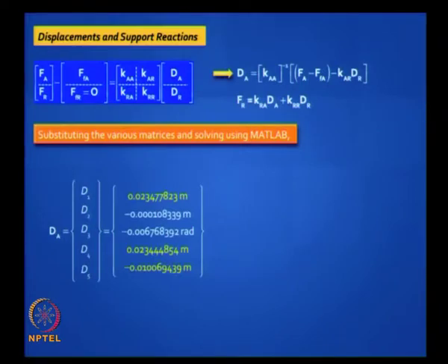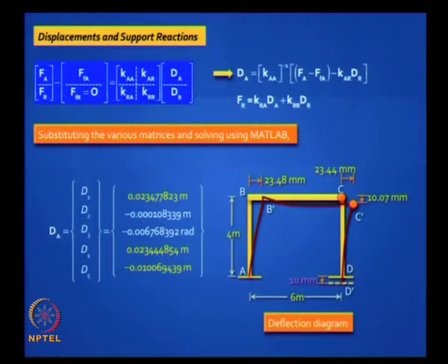Okay, that is it. Then you solve for the unknown equations, the method is the same, and you will notice that the deflections have increased substantially compared to the previous problem. Now you have a sway of 23.4 mm, that's how you interpret the dA vector. D1 is a sway you get at B, which is shown in yellow, and D4 is a sway you get at C. Okay.